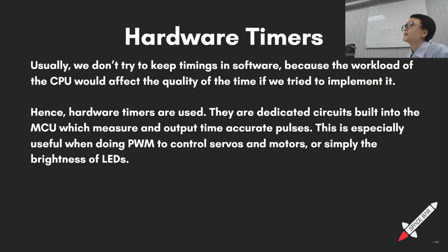It has GPIO pins that you declare to be transmit and receive, right? And then this is your sensor, which also has TX and RX. TX stands for transmit and RX stands for receive. And so typically when you wire things up, you have to cross them like this.